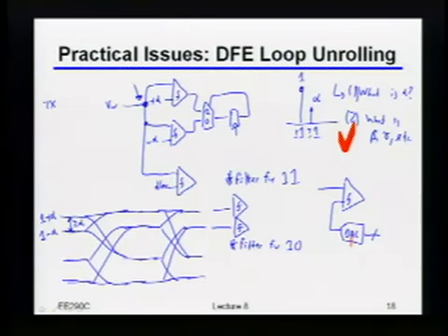The thing was, you do have a summation after the comparator. That thing was kind of like a low-pass filter, so essentially it helps you average out everything, including this mismatch from the DAC. Okay, so here's the problem. Remember, I'm running this thing at 10 gigabits per second. So if there's a big enough low-pass filter at that summing node, or 20 gigabits, or whatever frequency that I'm running it at, right? If there's a big enough low-pass filter that I'm actually averaging these DAC corrections out, guess what? I'm completely averaging the data out too, and then I'm making mistakes, right?